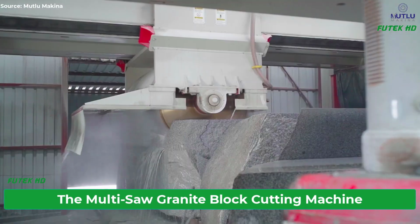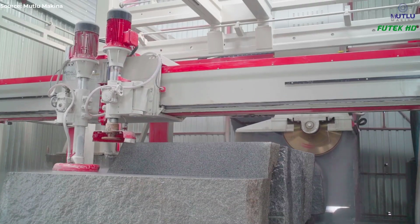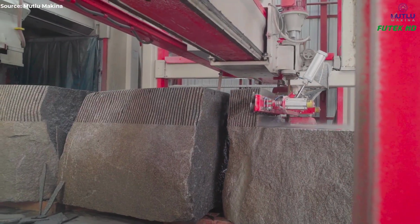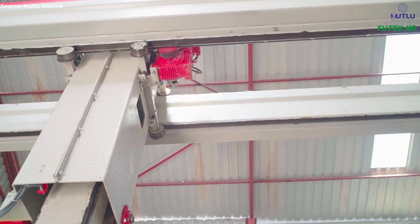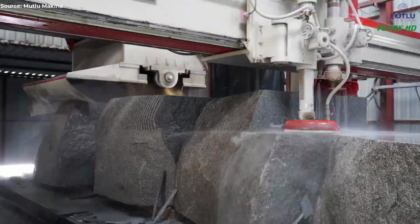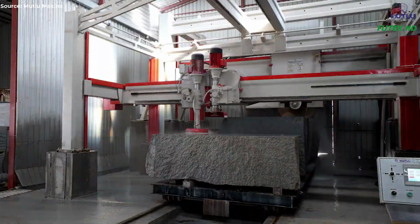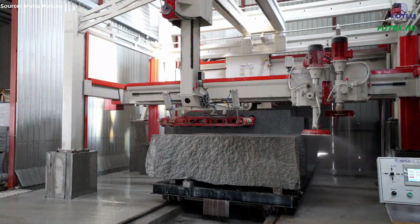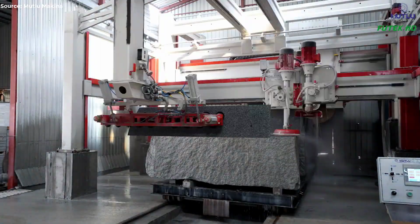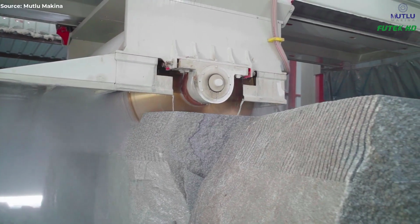The PLC-controlled multi-saw granite block cutting machine significantly enhances efficiency by saving manpower and time. It operates with a 200 kilowatts engine and is equipped with 64 saws, each 1,300 millimeters in length, allowing it to cut 2 to 3 slabs, each 480 millimeters wide. This machine, first manufactured in Turkey, can produce up to 300 square meters of granite slabs daily, which is 2.5 times more than the older model.